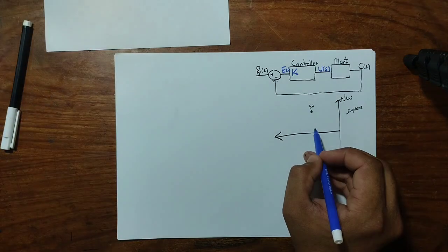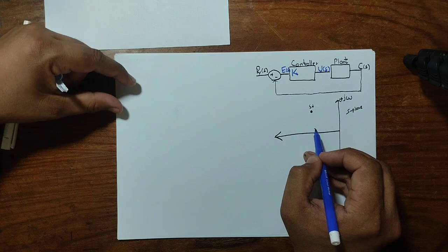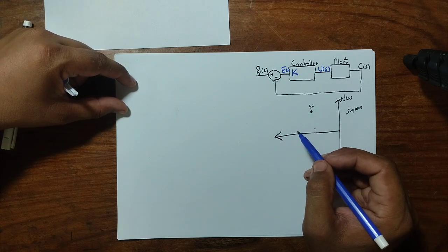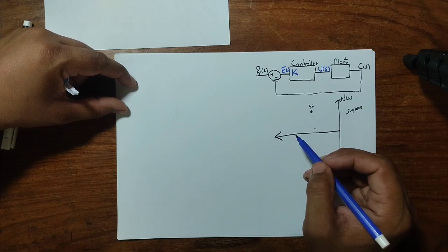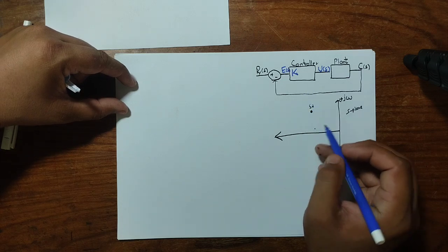So root locus is nothing new to us, as root locus implies that the closed loop roots will take some path to reach the open loop zeros of the system with a change in the controller parameter k. The controller parameter k is the overall system gain, and it can be adjusted so that our desired point can be met with the adjustment of this gain k.